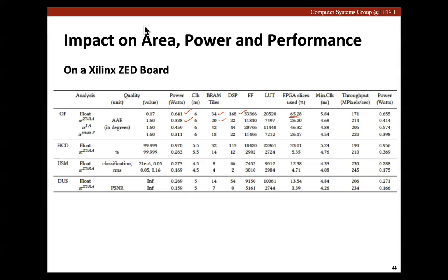And this particular thing you will not be able to make use of in CPUs and GPUs quite as well, because there the granularity of the data types is limited. They are very coarse grained. Like float, double, and I think these days 16-bit floating point numbers are also introduced. Perhaps given all the stuff in the deep learning space, maybe 8-bit floating point numbers might also have been introduced in GPUs or in CPUs. I'm not sure about CPUs though, but perhaps in GPUs they may have something like that. But in FPGAs, we have a whole lot of flexibility.